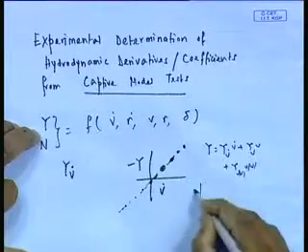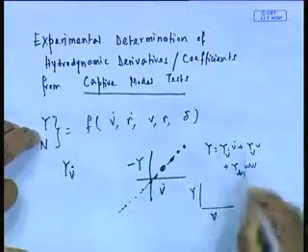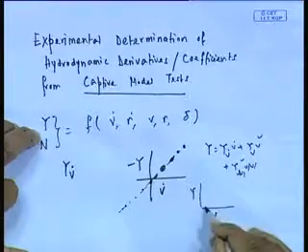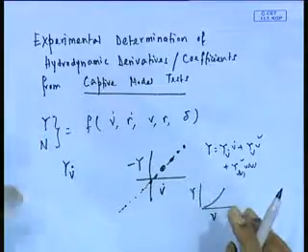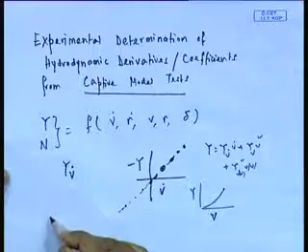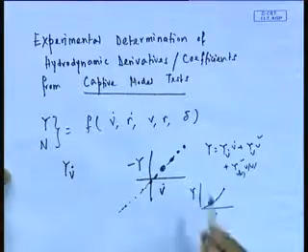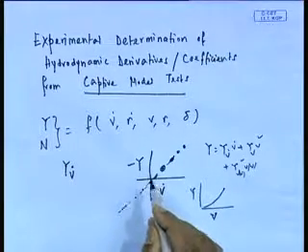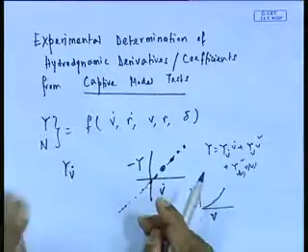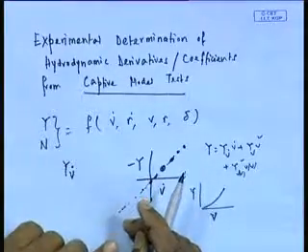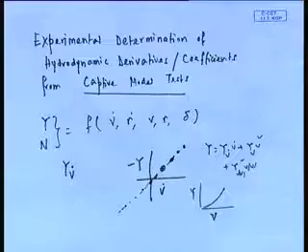If it is Y versus v, I can of course measure it, because I will have a graph like that. But I have to make sure that the other parameters are 0: if I want Y versus v, then v dot, r dot are 0, and delta is also 0. Delta 0 is not a problem as far as the experiment is concerned, but how do I do that? This is where the challenge of designing the test comes.